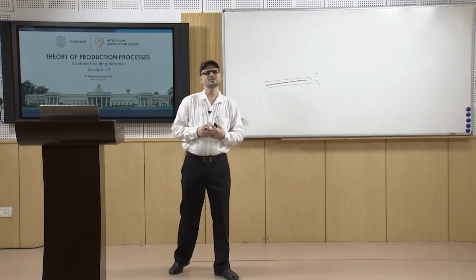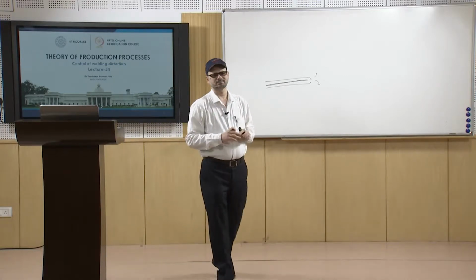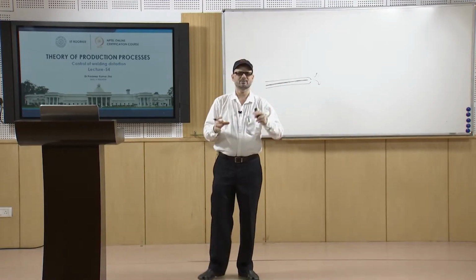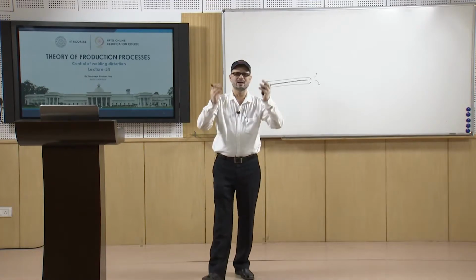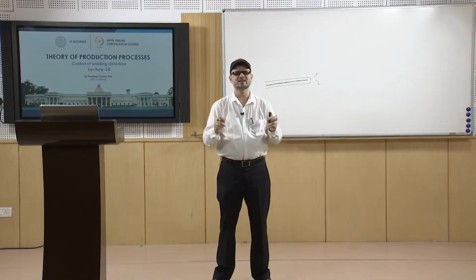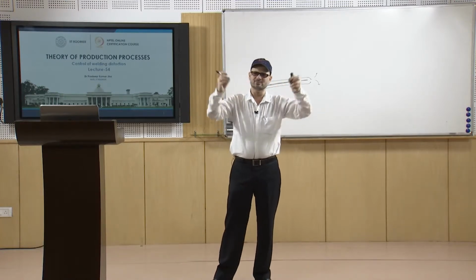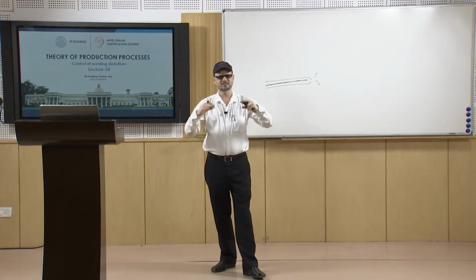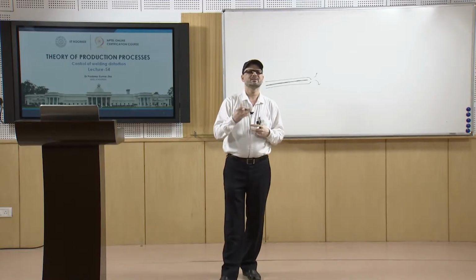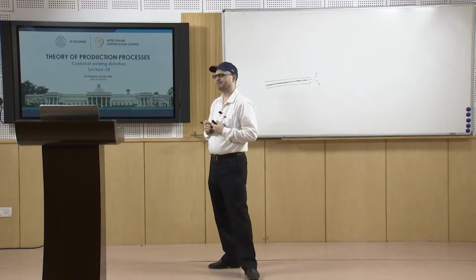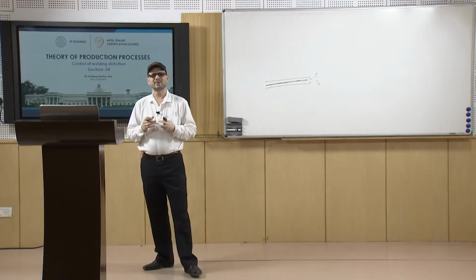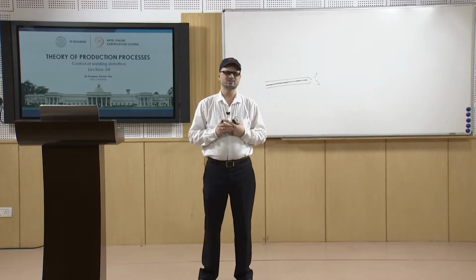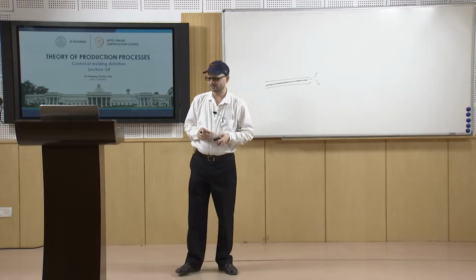Many a times you have a counter setup. Many a times what happens is that the welded structure bows, or it has a sagging type of tendency in one direction. So, you try to have a counter setup. Suppose it bows in this direction, you put the specimen itself in the opposite direction, so that even if there is a bowing in a certain direction, it will be flat even after the welding. So, this way you have different types of methods for controlling the distortion in the welds. We will discuss one by one all these methods.